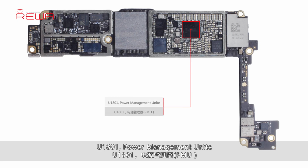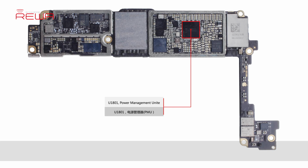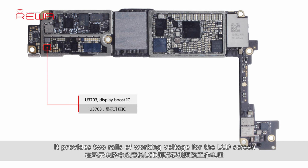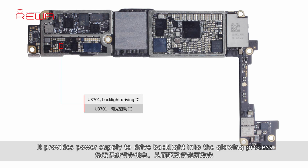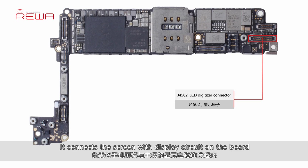U1801, Power Management Unit. It provides display enable signal and power supply for the display circuit. U3703, Display Boost IC. It provides two rails of working voltage for the LCD screen. U3701, Backlight Driving IC. It provides power supply to drive backlight into the glowing process. J4502, LCD Digitizer Connector. It connects the screen with display circuit on the board.